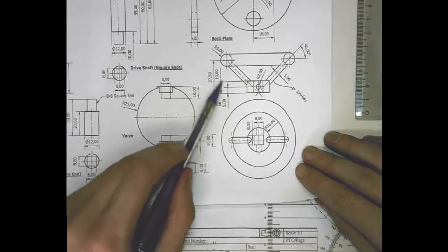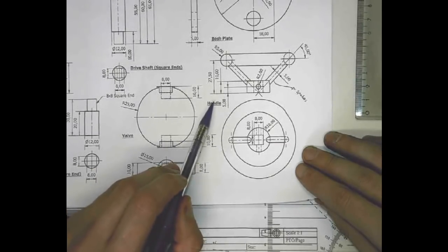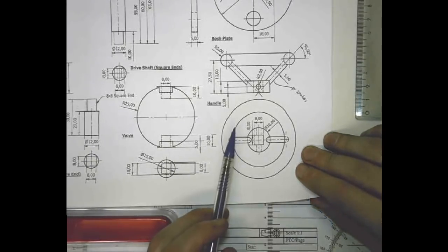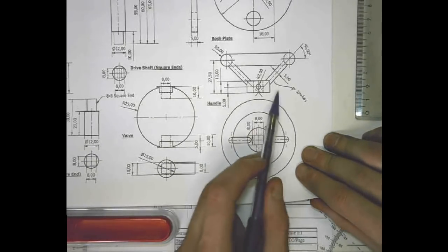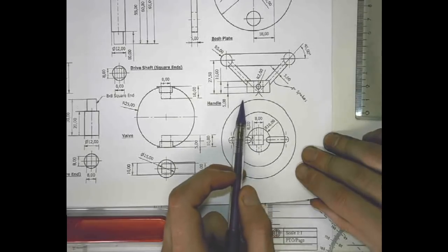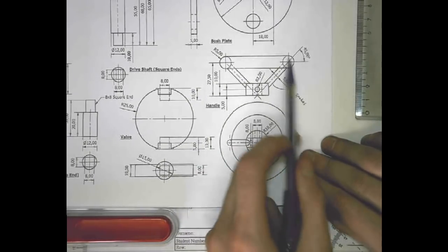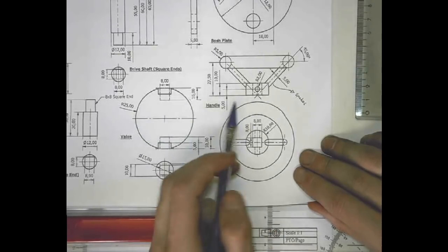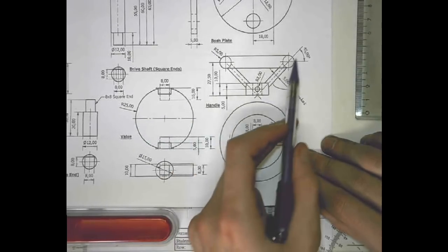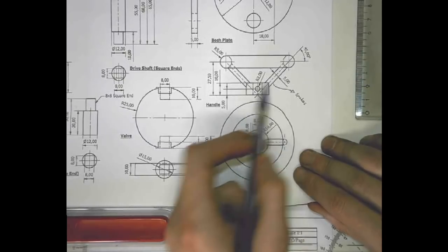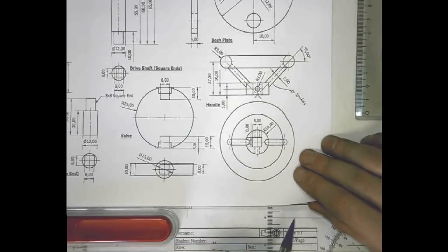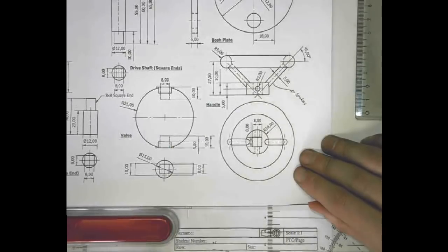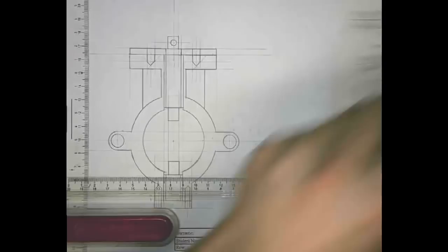This bottom section is 10mm high, and then the height or the width isn't directly given, but it'll be constructed from the 45-degree angle that the spokes come out at. And we can see that at this 45-degree angle, the vertices of that rectangular section are coincident. So we can get the width from those construction lines.